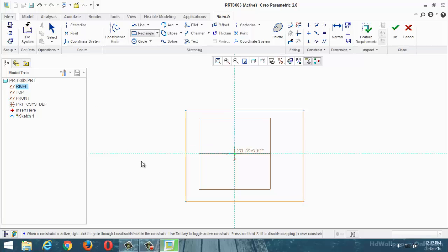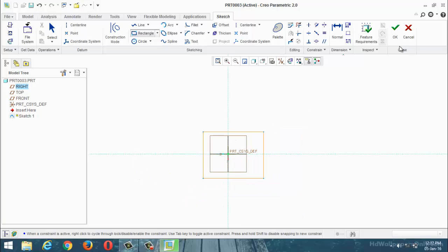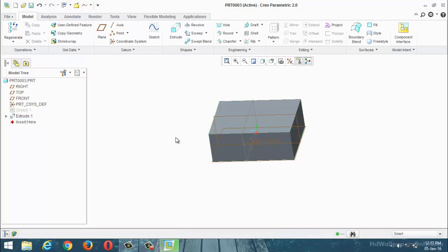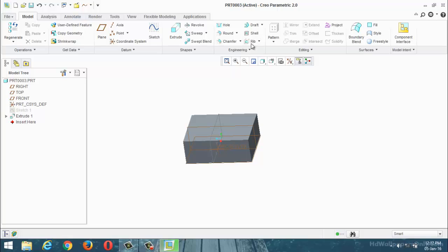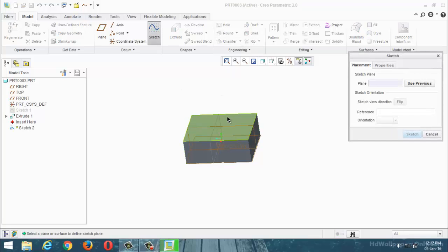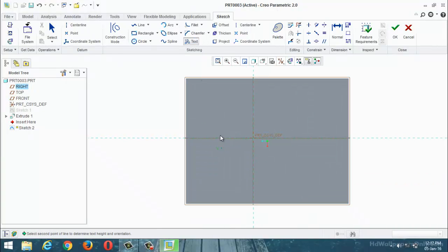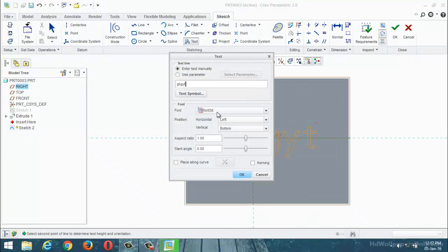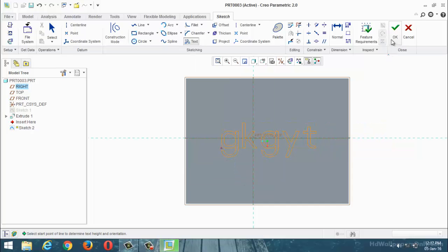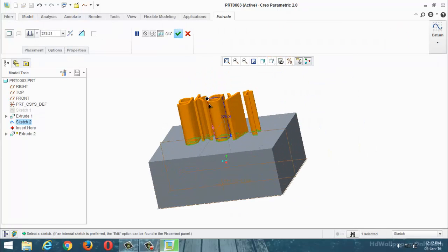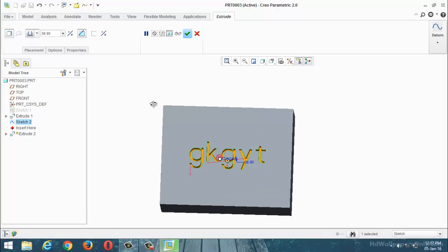Then we can see the next one. Then next, okay, extrude. Then I am going to design the text here. Now what is the process? Sketch, select this one, set to sketch view, text, height, okay. Just okay, apply the extrude, okay, then you can specify the value in this format. Then you can specify the inner direction, remove material.